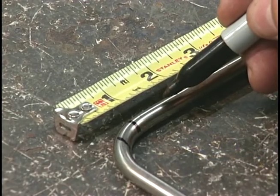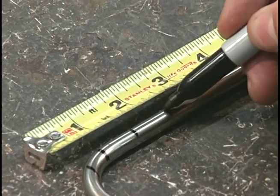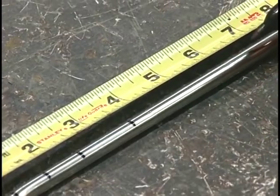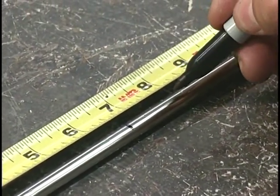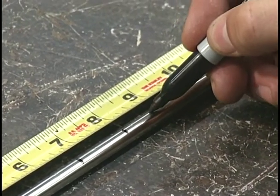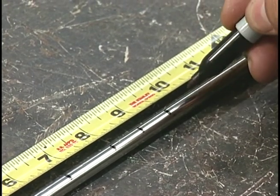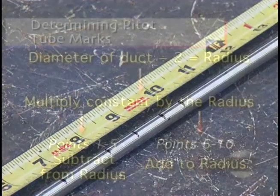In order to do the traverse, the technician marks the pitot tube with an erasable marker at 10 locations. The marks are based on the radius of the duct and a constant for each test point. The pitot tube is marked so that the technician can take 20 velocity pressure readings in the duct, 10 for each hole, at centers of equal concentric circles.